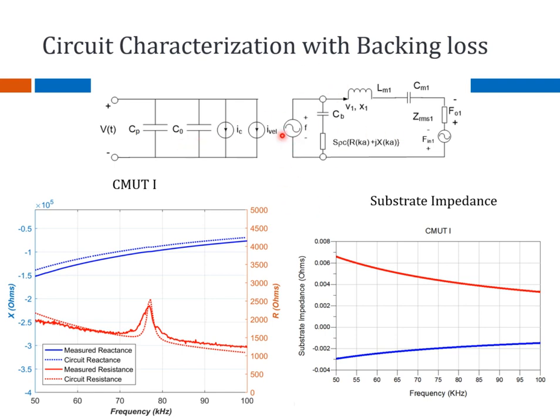On the electrical side, you also see the parasitic capacitance, which is required to move the simulated circuit reactance and make it closer to what you are measuring. So for example, this is the substrate impedance, and this is the RC shunt branch impedance that goes into the model, so that you have that elevated baseline and you can come closer to what is being measured.